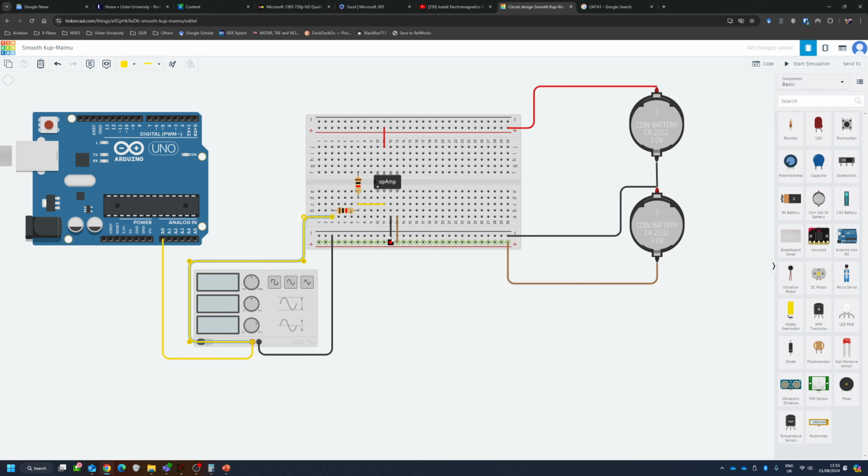Yes, now everything is alright. And let's connect our R2 to the output. So output is here. I'm going to connect my output signal into here. And because this is my output, I'm going to call it green. And from this green here, I'm going to connect to the analog 5 in the Arduino.